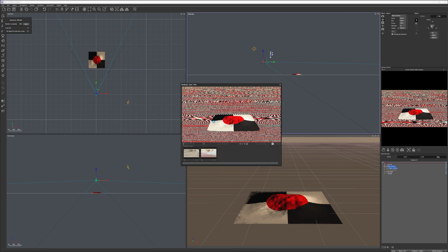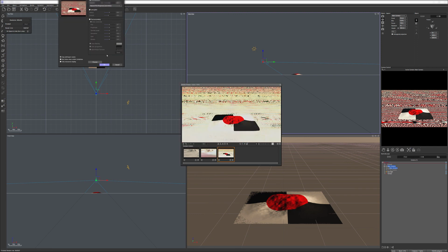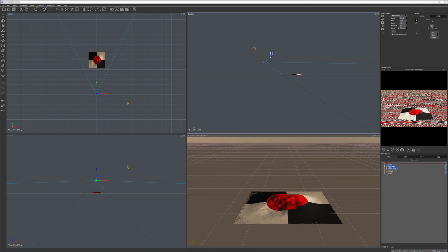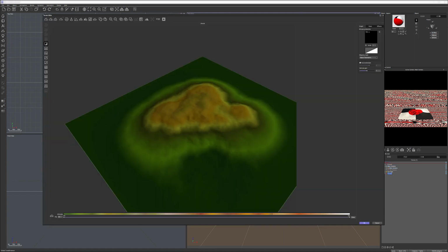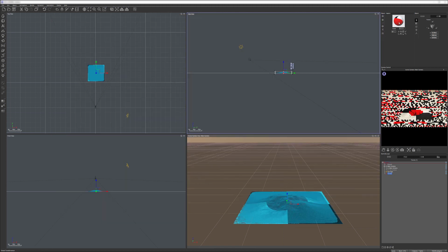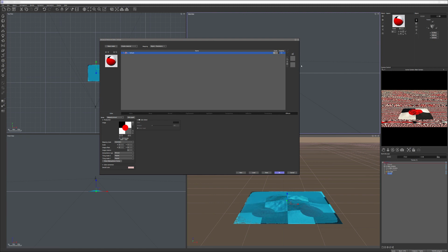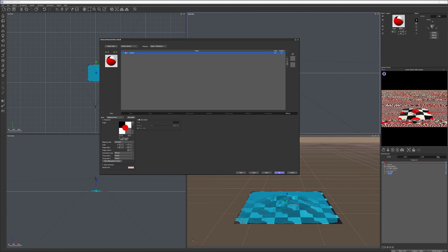Let's go pre-render. And you can see we applied our image. So it takes one single image and it's stretching. We could change some of the sizes of this if we're going inside the terrain material editor on terrain. If we do on a scale, for example, 0.5, let's do half scale, and you can see we can manage and manipulate scale on our procedural terrain.